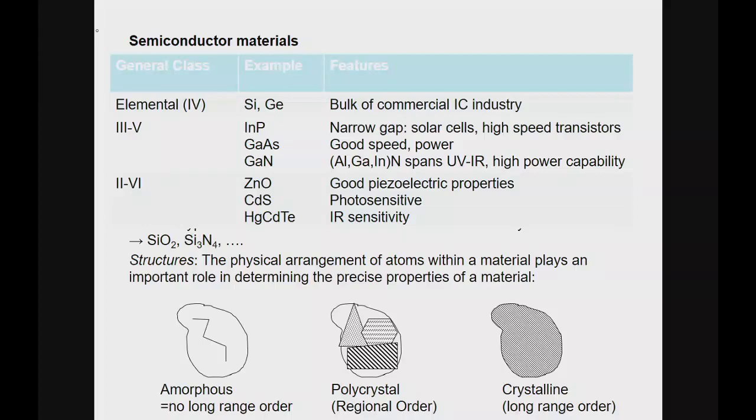One area it can't work is in optoelectronics. You can't make a laser using silicon, but you can make it out of gallium arsenide. So that's one area where silicon is not really cost effective. Even high-speed silicon devices can get very high speed these days, but one of the market areas was gallium arsenide and gallium nitride. Of course, you're all familiar with that, the recent Nobel Prize for the blue LED. So gallium nitride is sort of a semiconductor semi-insulator. It has a very wide bandgap, so we'll learn what that means later on.